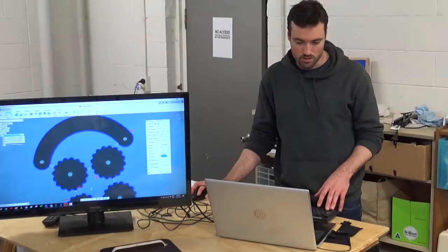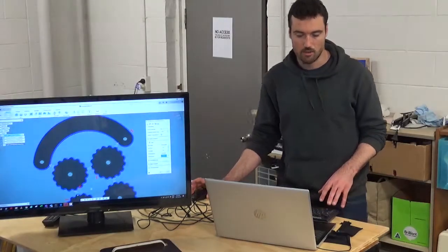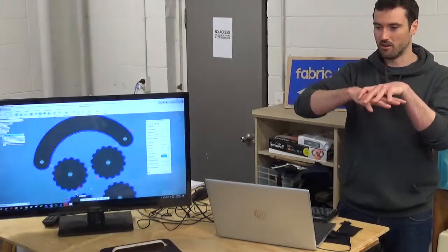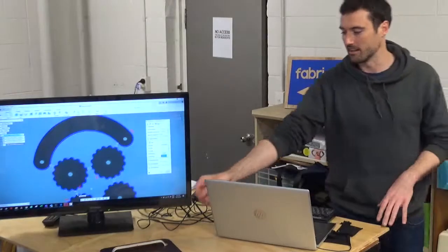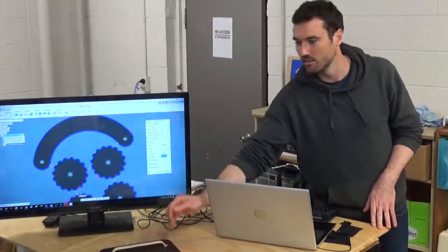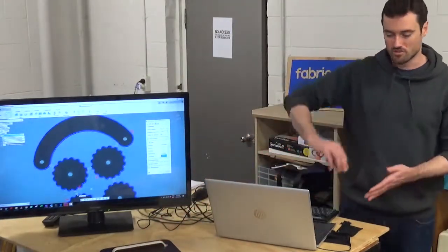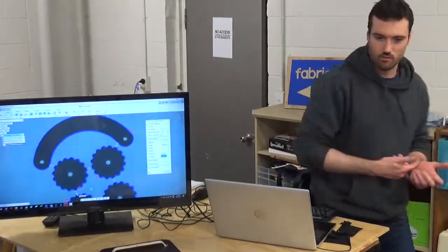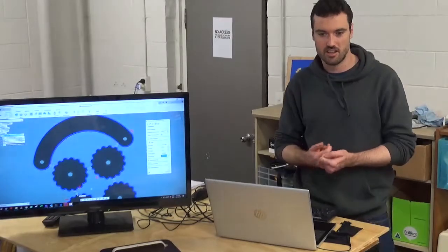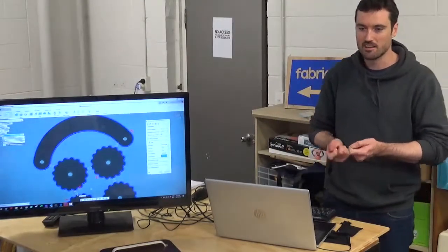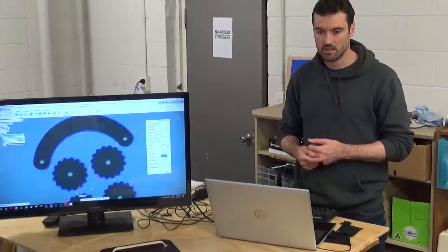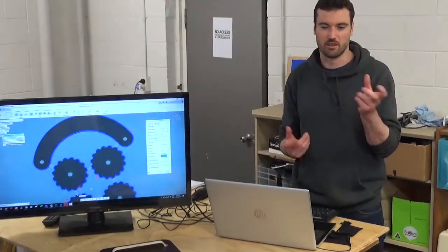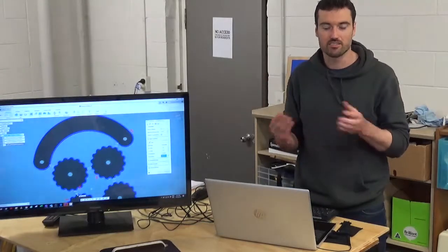If you're using plywood, plywood's only really strong if you've got both directions. So you want to get at least 2 plies, even more, because when you're going over the tab, you still have to deal with all these twisting forces. So they still have to be beefy enough to stand up to that. So should it be thinner or thicker? Thicker. You probably want 3 plies, I think intuitively is a good amount.